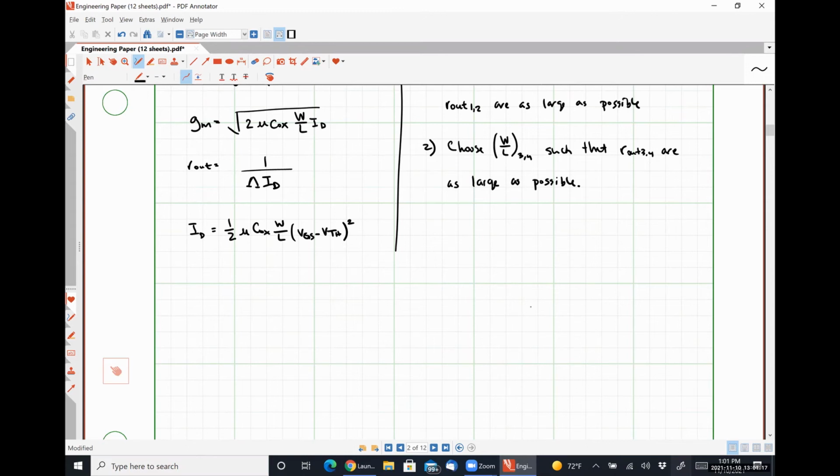So effectively, we maximize R out by making that current source transistor effectively as large as we can make it for our given footprint, which has the added benefit of making that DC bias current ID5 as stable as possible, because we're making it less subject to channel length modulation shifts as well.